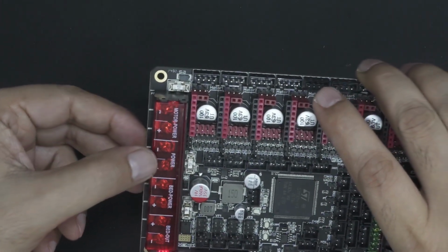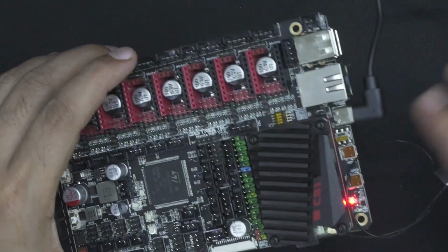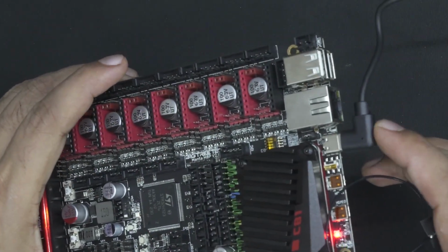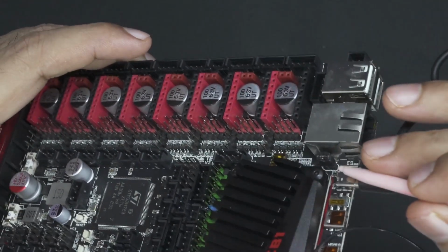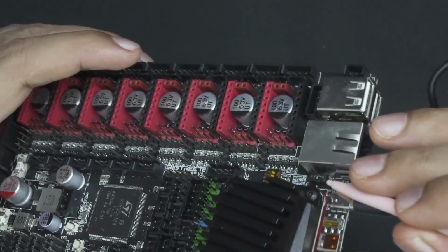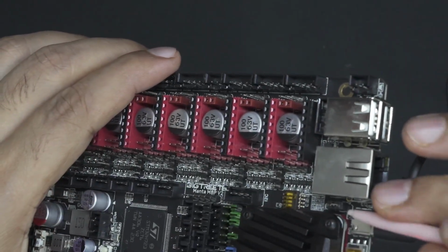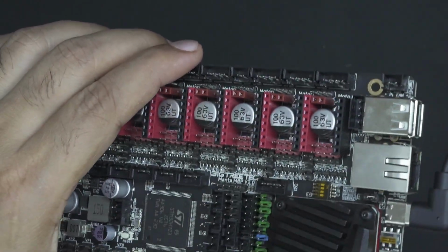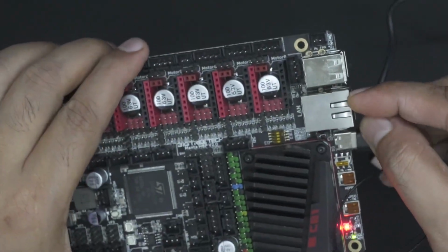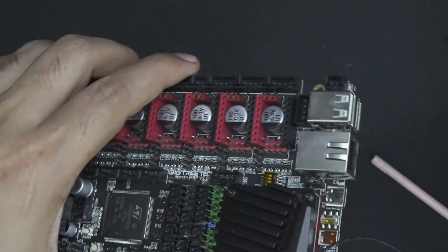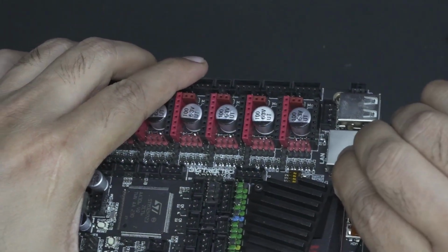So DC voltage you have to put over here, and once you do that, we have to disconnect the USB cable and also remove the jumper. So there is a jumper over here, you can see. When you are powering the board from this power unit, we need to remove this jumper. So let's do that now. So I've disconnected the power and I will remove this jumper.